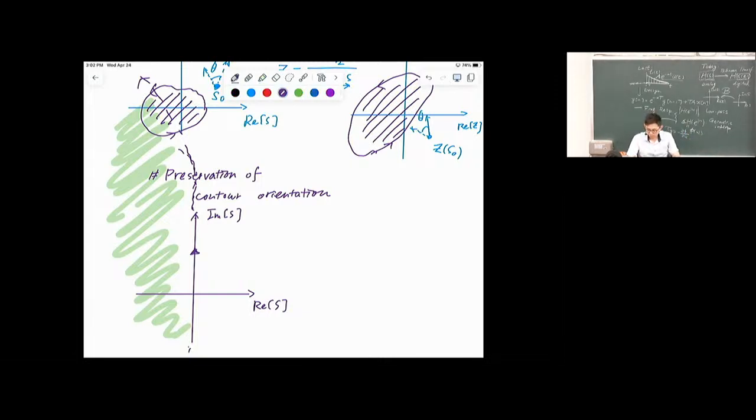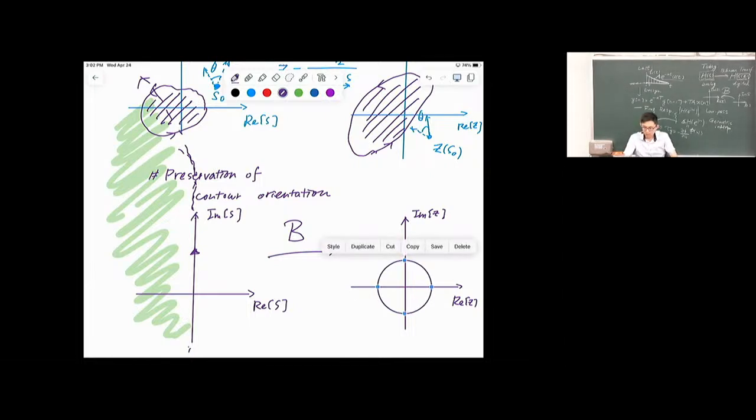So we can be sure that when we apply bilinear transformation to go to the Z domain, not only does the imaginary axis map to the unit circle, and we have just proved that, okay? But the left-hand side remains on the left-hand side. The inside remains on the inside, okay? That's what it means for conformal mapping to preserve orientation.